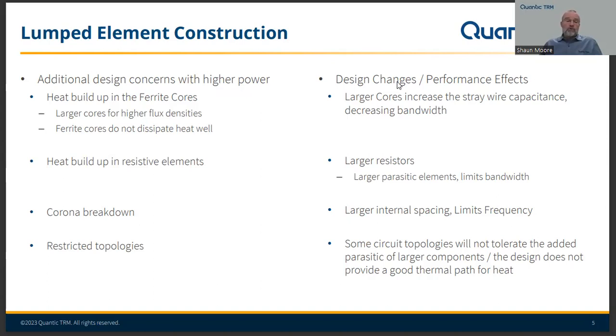Here, when you get into either wire wound inductors or using coaxial structures to help build these transformers, the stray reactance off of the larger wires and cables really becomes very significant and something that definitely needs to be accounted for when going into the design.